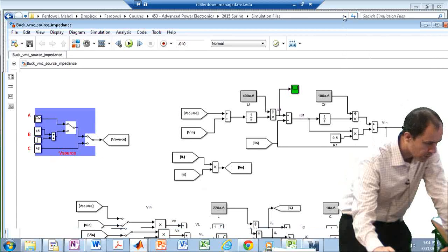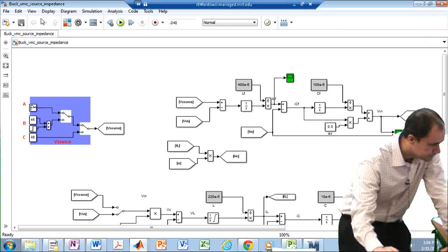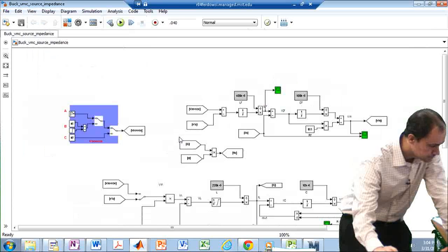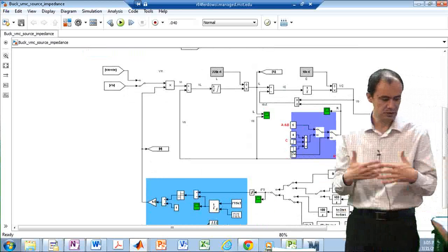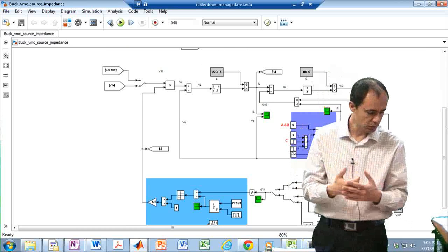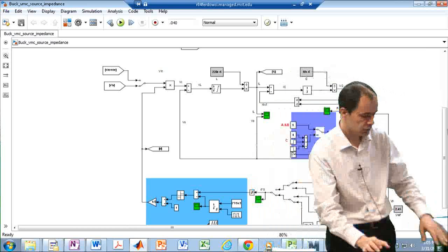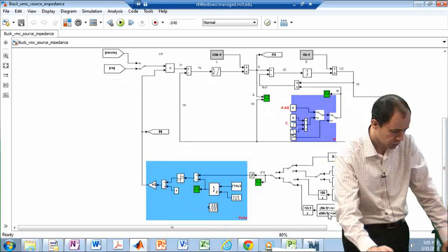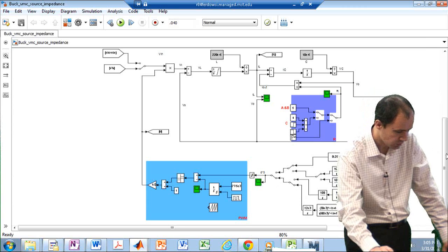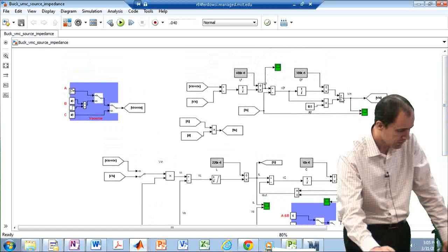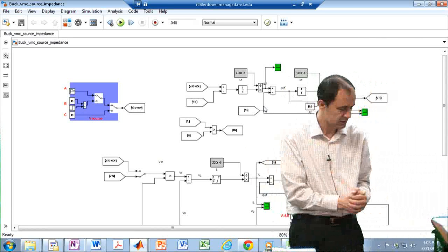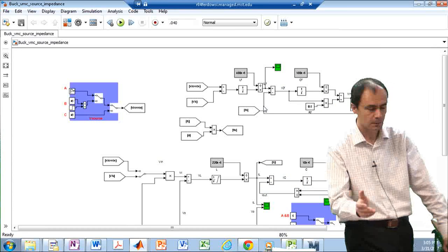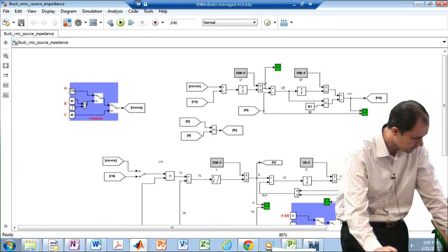All right. So here in the bottom, I have my classic DC to DC, in this case, the Buck topology, and it is controlled by a voltage mode controller. So I have this voltage mode control block over here. This is my selected transfer function or compensation network. On the input side, I have added an LC filter, and it doesn't look like an LC filter, but the math is following the math of an LC filter. Obviously, if you're doing Plexim, it would look like an LC filter.